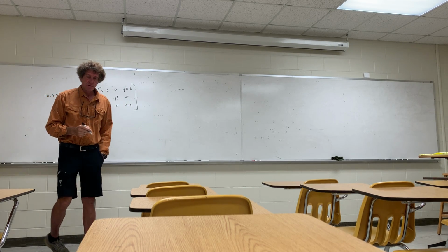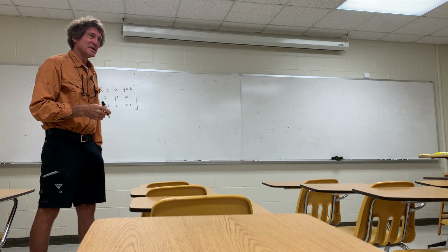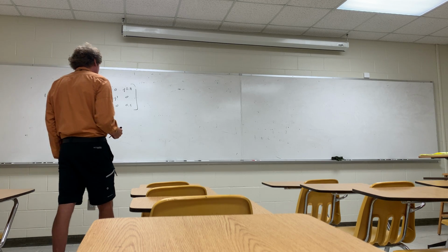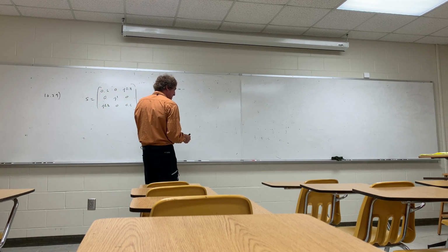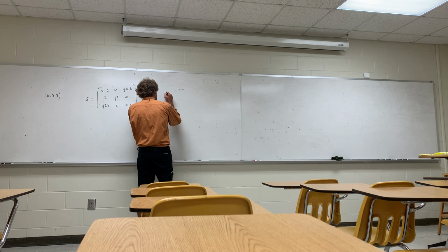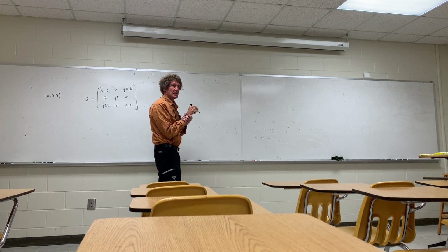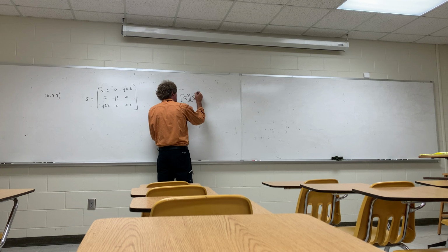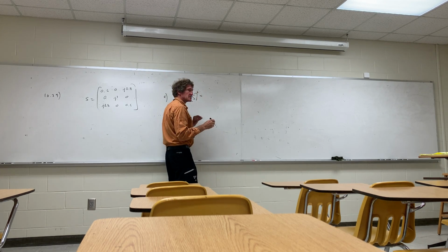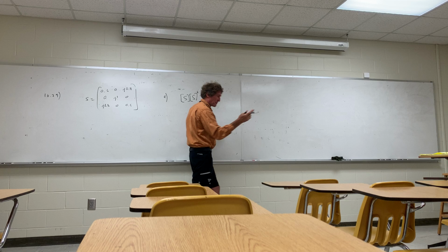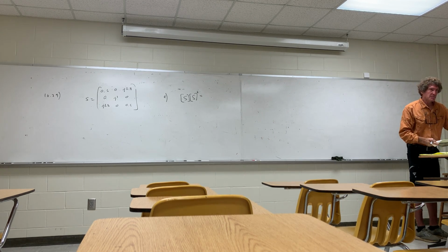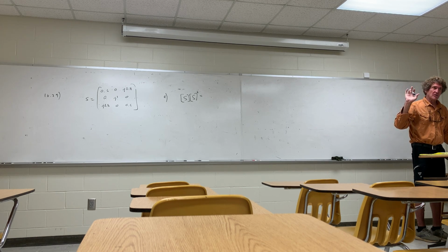What do they ask? Is it reciprocal? Is it lossless? And determine the return loss at port 1 when ports 2 and 3 are connected together. All right, first part is it a reciprocal network, right? I'm not going to test on that. Reciprocal network means that the parameters are the same looking forward or backward.